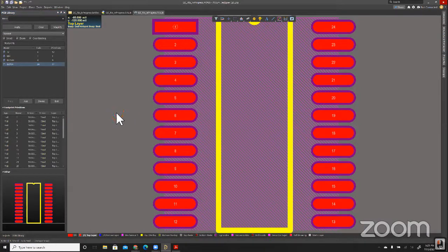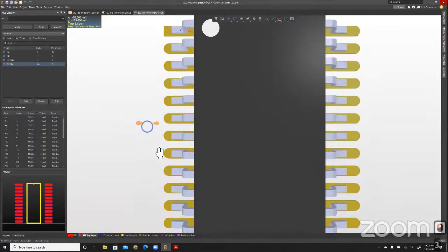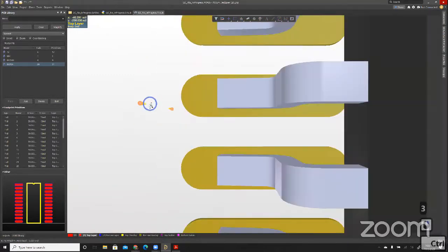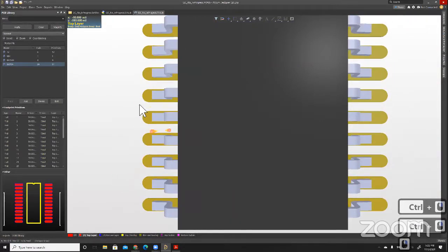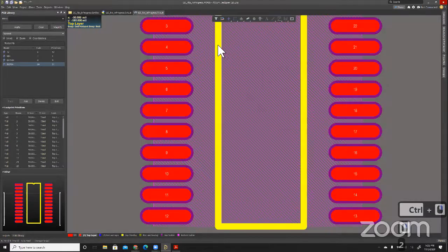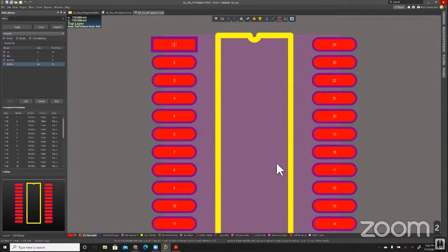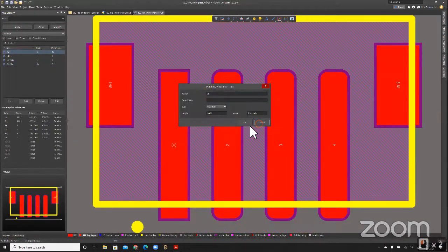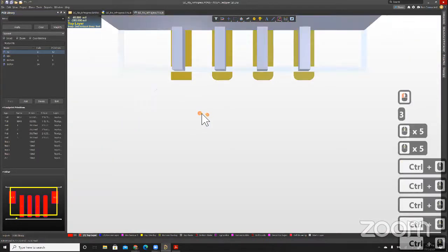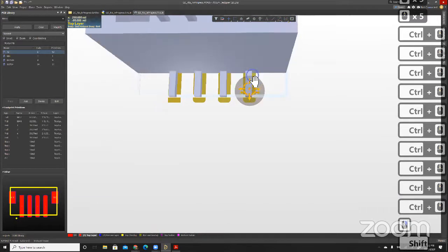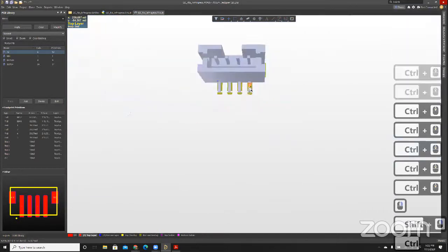Something that's kind of nice is that in Altium you can hit 3 to go to 3D mode. I've actually placed 3D step models of the parts on them. I find that to be helpful to make sure that I got the footprint correct, and I can go and add additional lines if I want to about all this. I'm going to probably do a little bit of an example of that later if I can. But I find that useful to make sure that I know how big things are on the board and that I didn't accidentally use the wrong units or anything like that. So when you look at these things, you can make sure that all your pins line up and that there's no problems there.